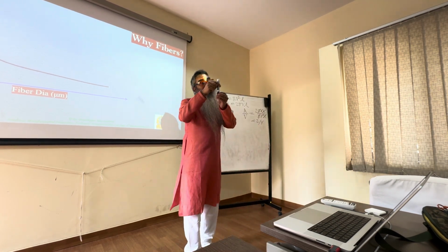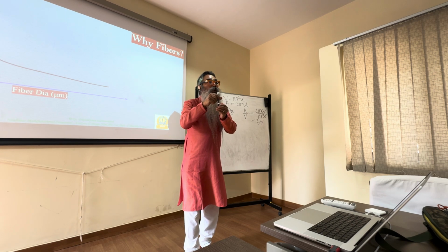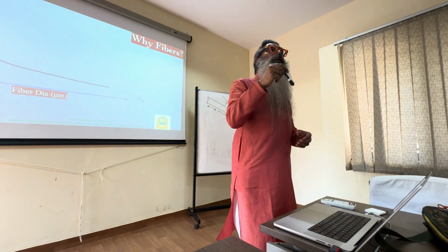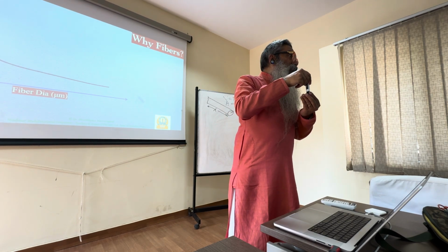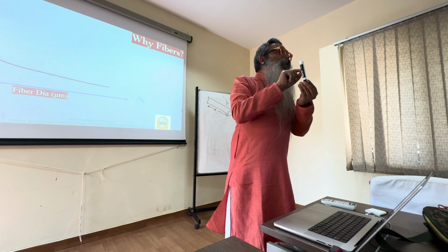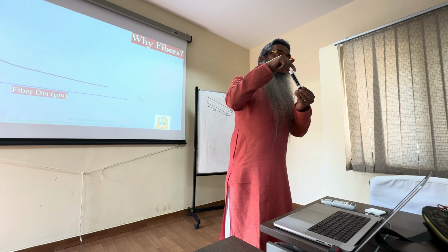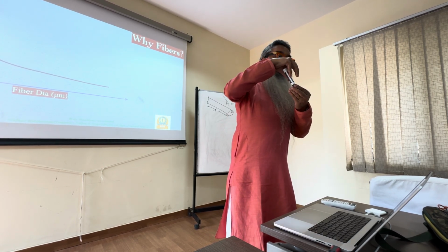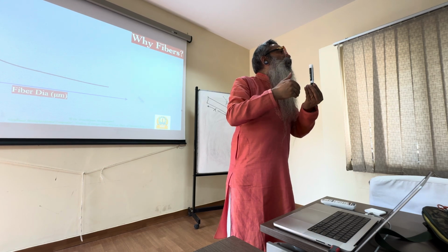So the more area you have for a given volume, the more the chances of a defect. Okay, because there's something called the surface defect density. The number of cracks times each of their lengths, if you add up and divide by the area, is essentially the surface crack density.